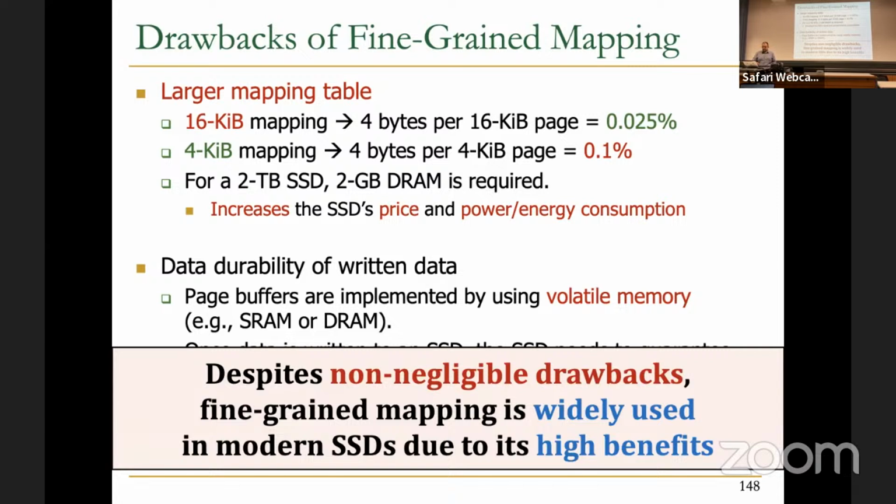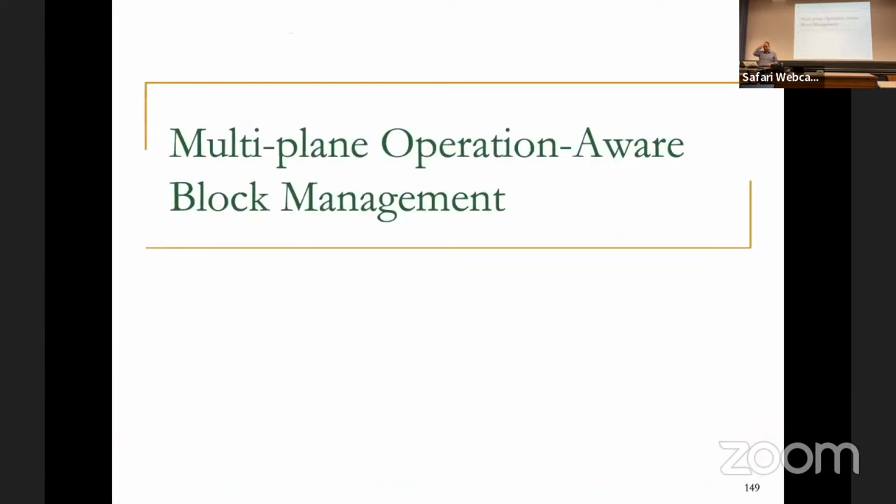Yeah, but despite the non-negligible drawbacks and overheads of fine-grained mapping, this has actually been used significantly in enterprise SSDs. Mobile SSDs might not actually use it because they really need to keep costs low. But enterprise SSDs are all using this fine-grained mapping.